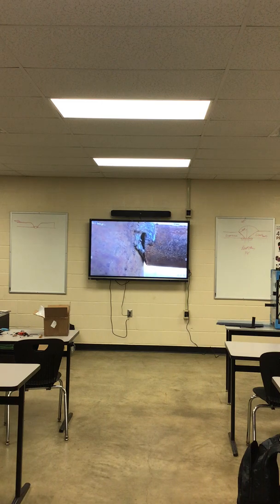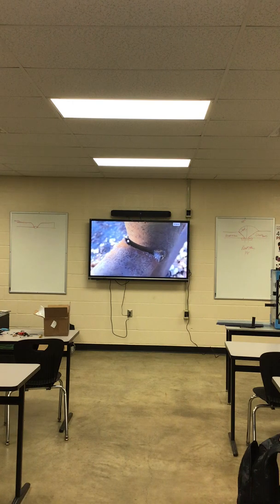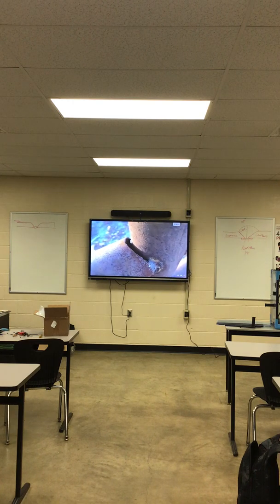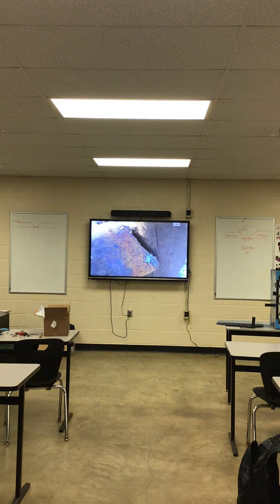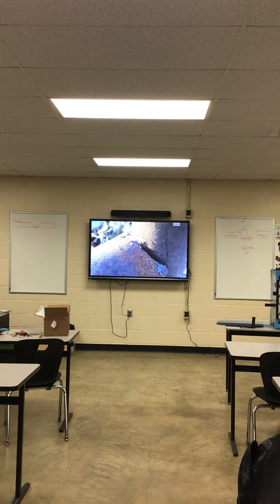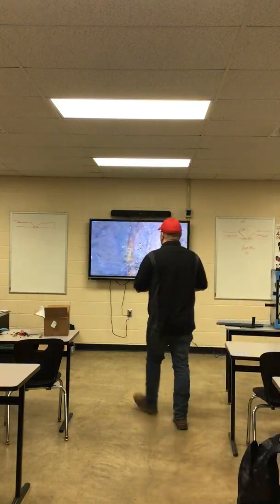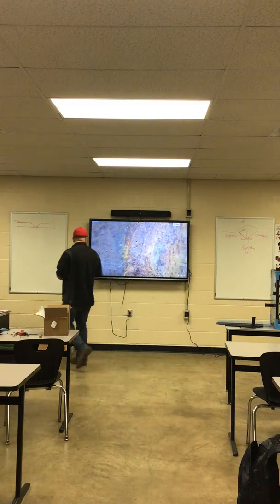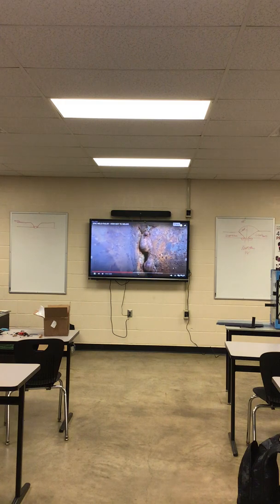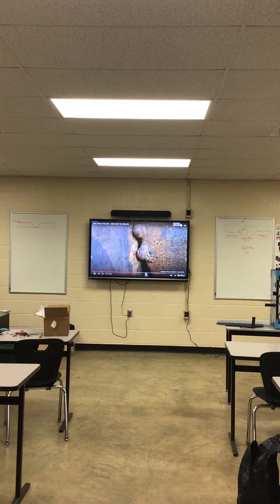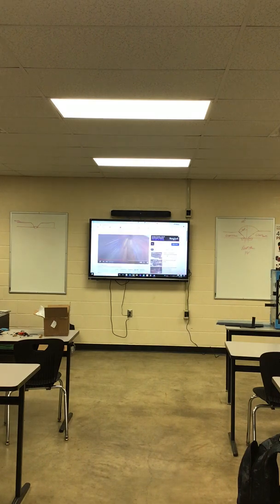So we're going to start with poor fit up right away. Huge gaps. A lot of porosity, a lot of slag inclusions. You guys know what causes those, correct? Lack of cleaning? Unclean base material? Okay.